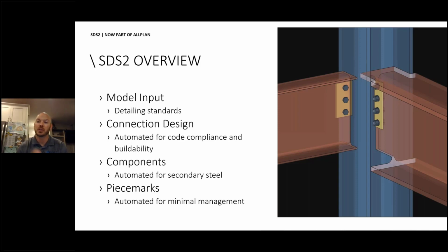We also design for the entire joint, the entire node. There's a good picture of that here on the right-hand side, where the bottom flange is coped automatically to clear the shear plate when it's dropped in. And this wide flange beam framing to the wide flange column is about as wide as that column is deep, so SDS2 recognizes that and copes out those top flanges to clear the column it's framing to as well.